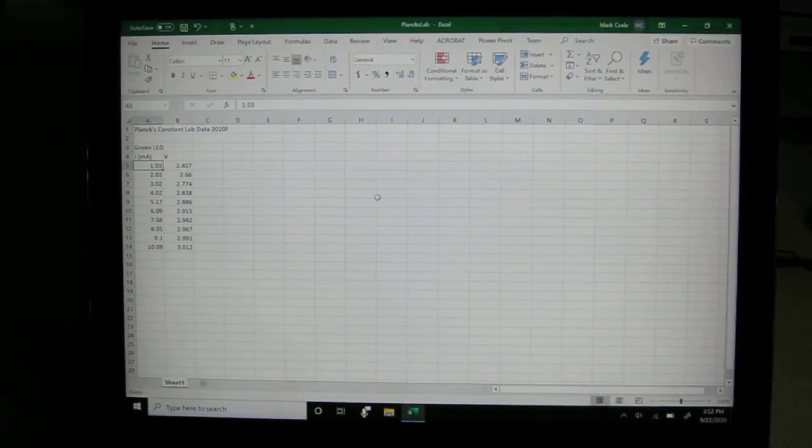With the points already loaded into Excel, we now wish to graph them as a series of X and Y points. In reality, the voltage will be on the x-axis, while the current will be on the y-axis. We do this because we want to extrapolate to the point where current is 0. That will automatically remove any of the effects of impurities within the band gap itself and give us a true indication of what the actual band gap voltage is.